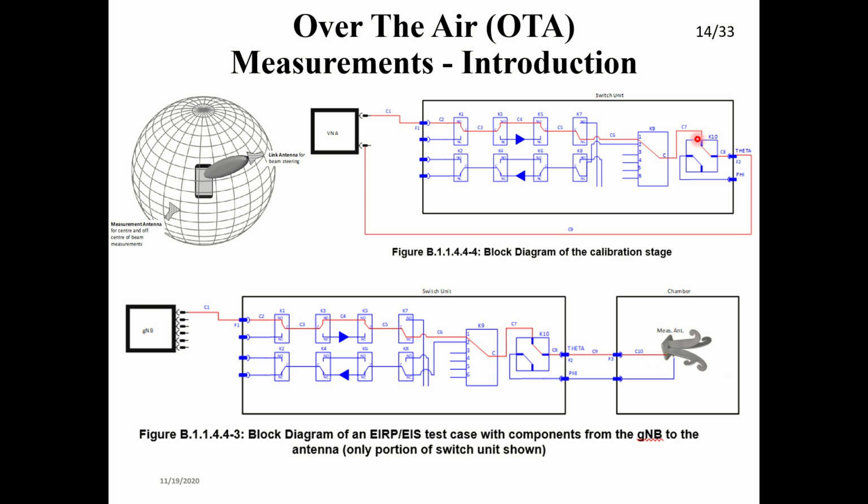So what you can find is, you are sending your power. S21 is what? Our output power divided by input power. Or if you call it as voltage, then it is output by input. This is the output power, this is the input power. If you take the ratio, you will get the difference between what you are sending and what you are receiving. Then you have to compensate those things.